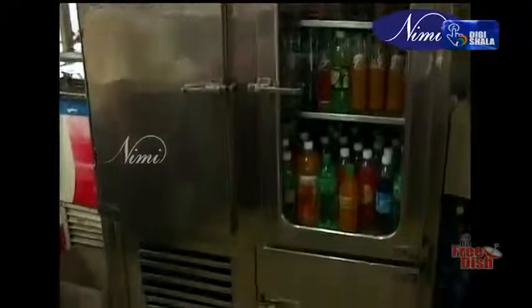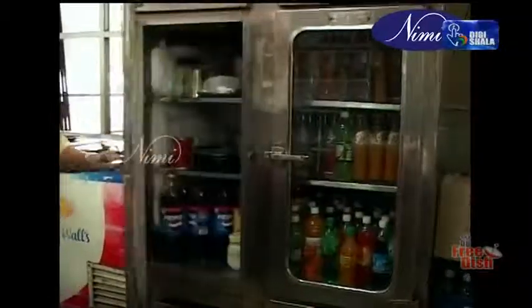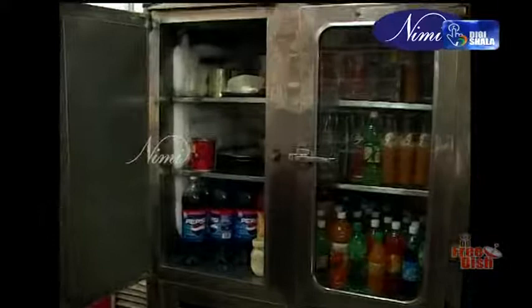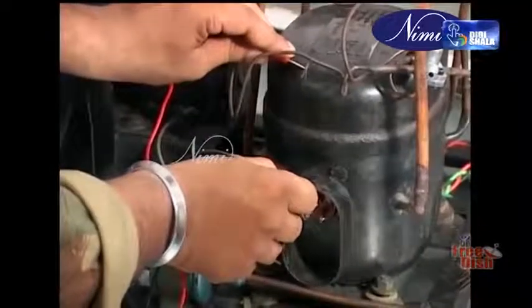Freezers. There are two types of freezers. One is chest type and another one is upright freezer. Upright freezer. The basic refrigeration system is used on all upright freezers. The only variation is the use of a fan-cooled condenser located under the cabinet in a few models. Other upright freezers use a static condenser located on the back of the cabinet. All units are of conventional hermetically sealed design.